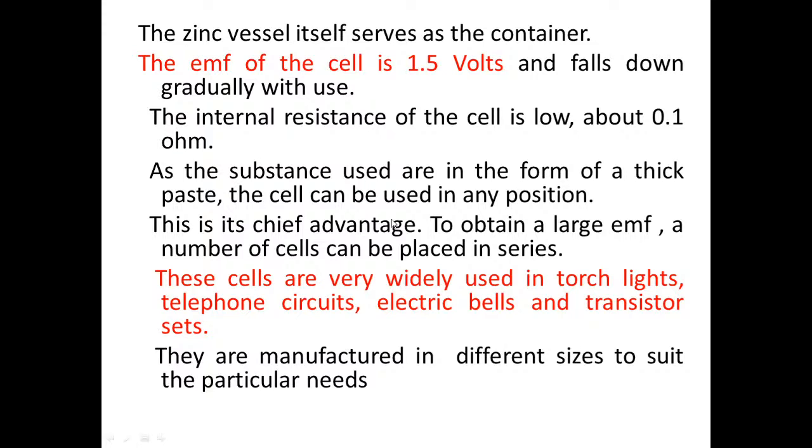The EMF of the cell is 1.5 volts and it falls down gradually with the use. The internal resistance of the cell is low, about 0.1 ohm. As the substances used are in the form of a thick paste, the cell can be used in any position. This is its chief advantage. To obtain large EMF, a number of cells can be placed in series.